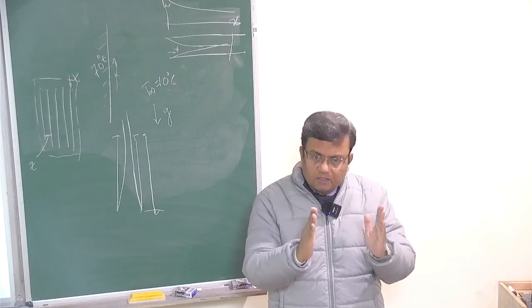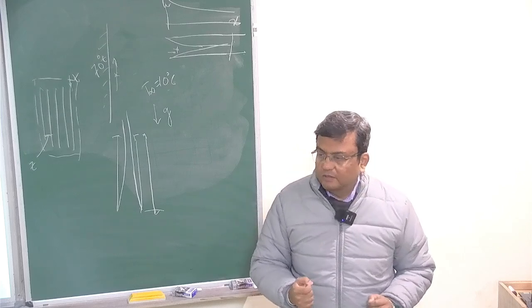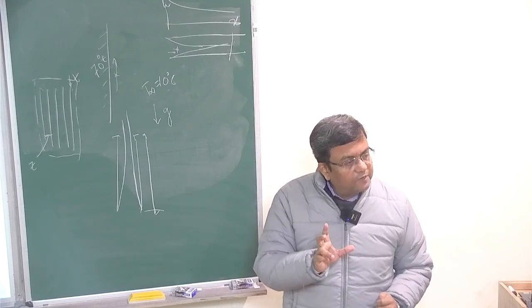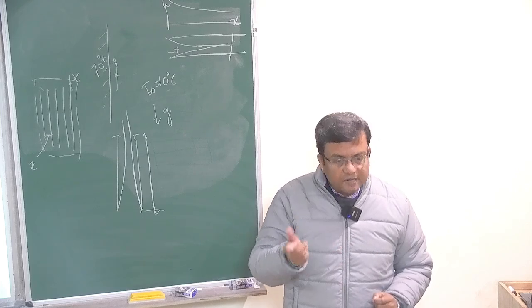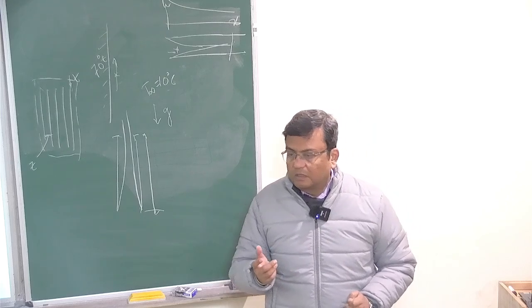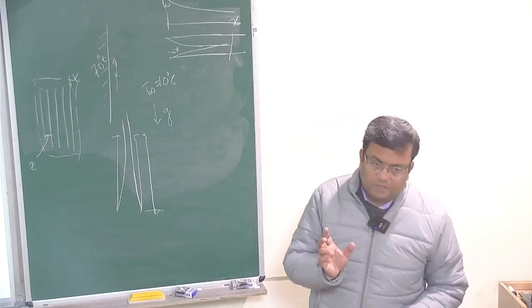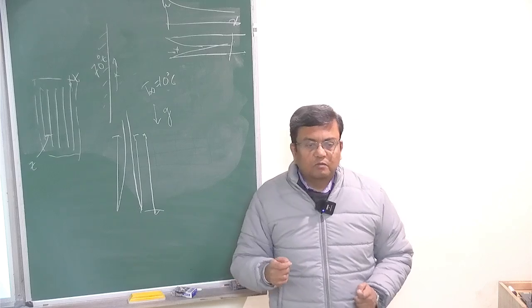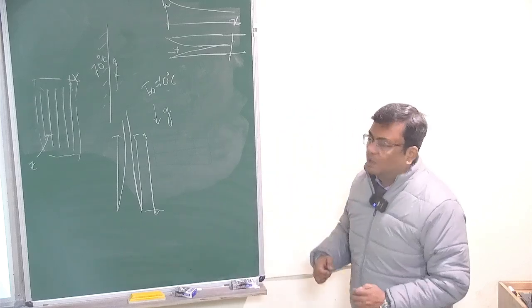But if you make the distance quite large, then you lose on the area, right? Because the number of channels, hence the number of fins, will also decrease if you have large spacing, correct? This is what Amila was saying some time back. Okay, so there will be an optimum.